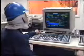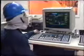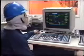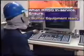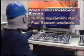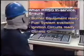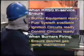Operation of the fired burners is automated, but operator attention is still required. When the HRSG is in service, make sure that the burner equipment is always ready for operation. Ensure that the fuel system is available and ignition and control circuits are ready. When the burners are actually firing, make sure that the control system is functioning correctly to maintain the desired gas temperature.